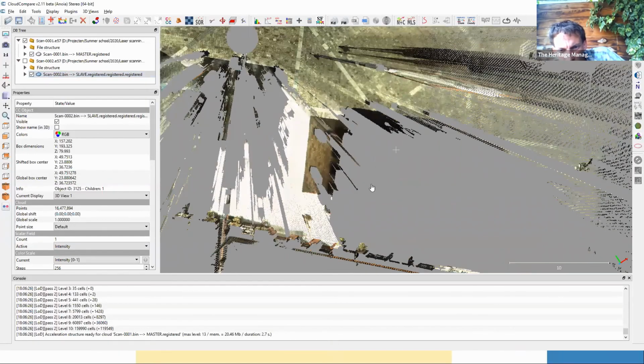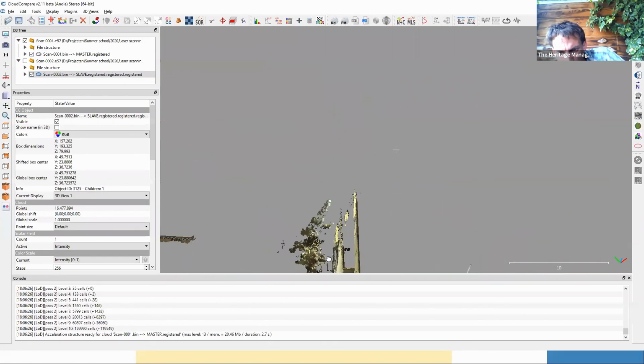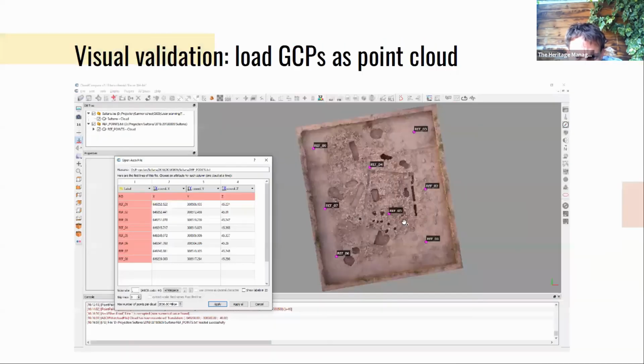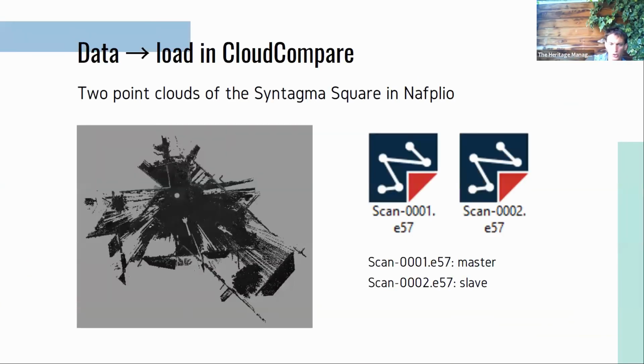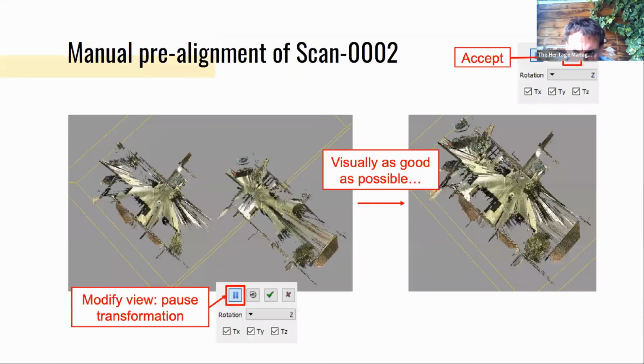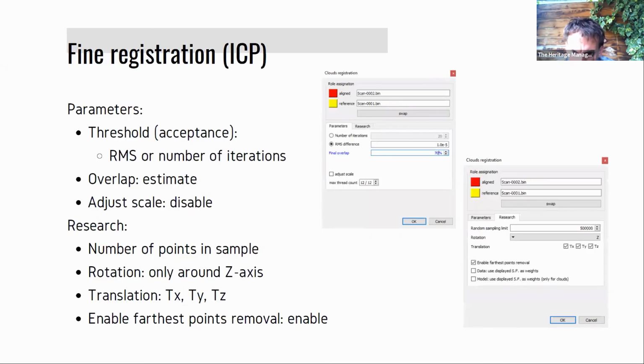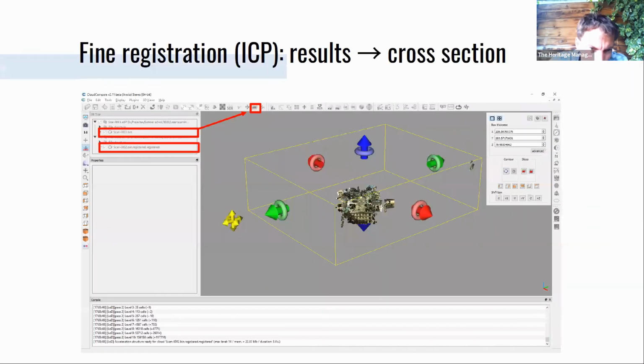And I can just continue this process until I have an optimized mesh. Eventually, when you are finished with this registration, so you will also do this registration in the exercise, please start with 2 scans and then iteratively you can add another scan. So try to work in a sequential order in that case. So once again here, step by step, the different parameters, the parameters for the transformation itself, acceptable, not acceptable.